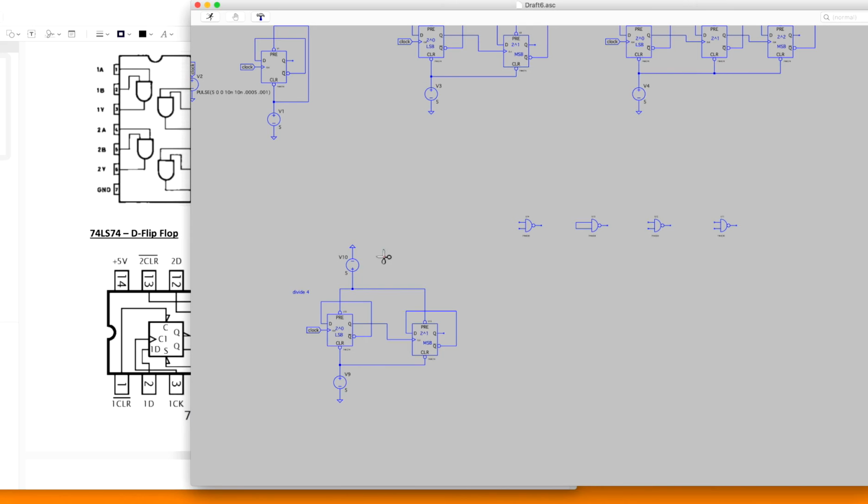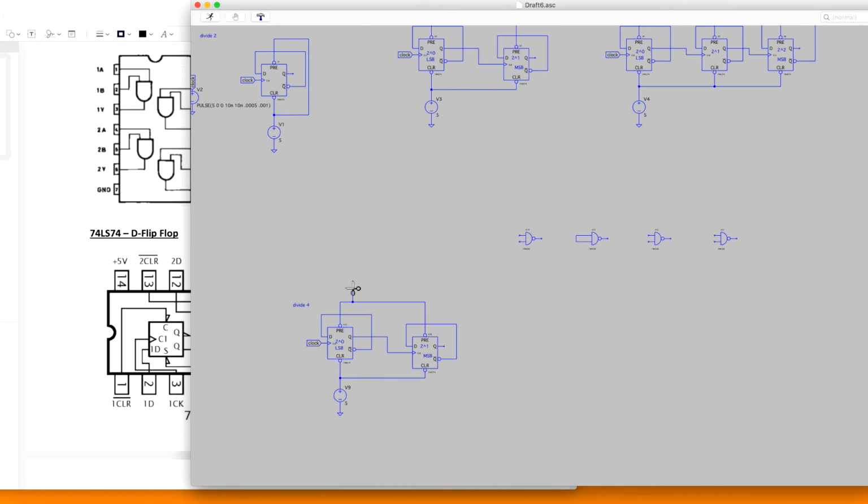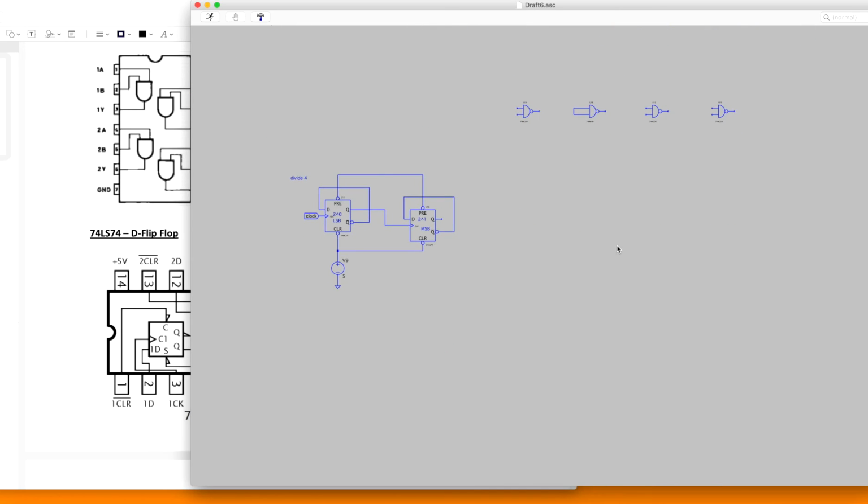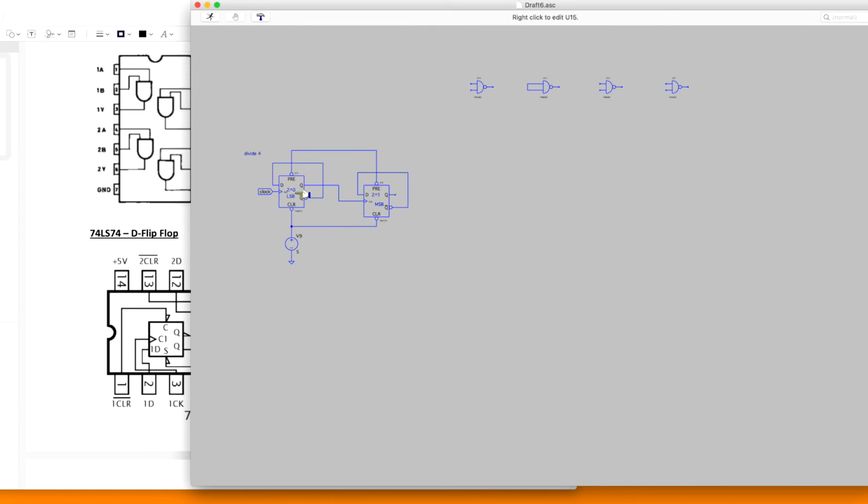And we are going to disconnect the preset node from the DC power supply. So now we need to decide which bits we need to use. In this case, we're going to need to use all of them. This represents 1, this represents 2. 1 plus 2 is 3. Okay? So that's how we create our divide by 3. We do it using NAND gates.